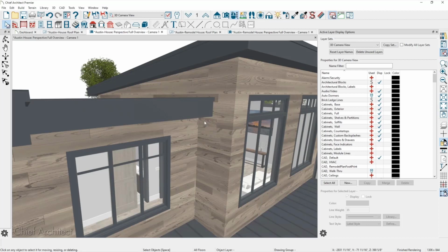Okay, so my situation is I have a cathedral ceiling living room butted up against the second floor bedroom that is higher than the plane over the living room, and the glulam that's scheduled to go alongside the framing of the second floor bedroom to support the roof.